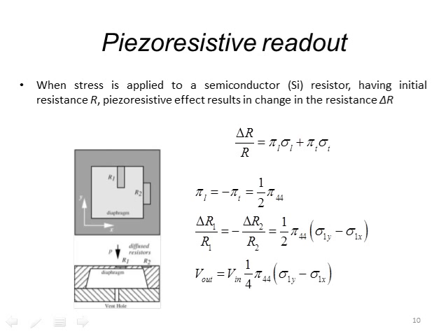So in this case, if a pressure is applied to the top of the pressure sensor, which is greater than the pressure in the cavity, which you can see on the bottom image, then the membrane or the plate is going to deflect down.